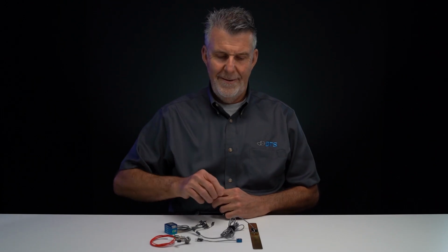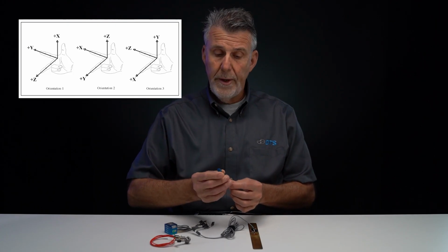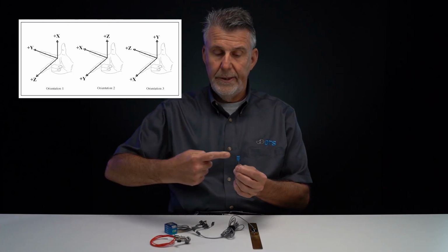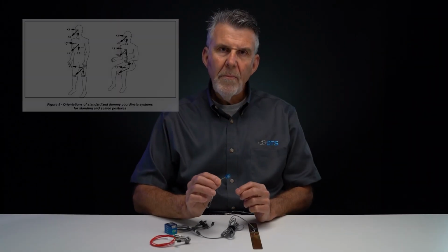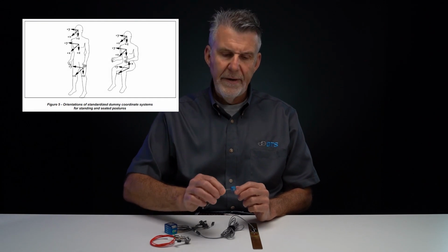Section 7 is entitled Sign Conventions. But what does that really mean? Well, any measurement you take will have an active axis. For example, with this angular rate sensor, its active axis is perpendicular to the mounting flange. So number one, if I mount that sensor in this axis, I need to have it properly labeled. Second, it will have a polarity. If I rotate it one way or the other, it'll give me a plus or a minus output. It's important that all measurements follow a consistent sign convention, and SAE J211 Section 7 helps us accomplish that goal.